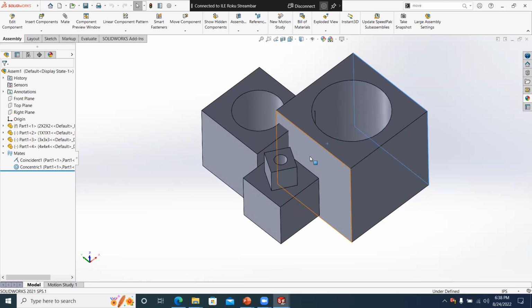Now they're separate, so you control the configurations within your part, and then the assembly is managing each of those parts on its configuration level. So if I brought in a pin to go inside of these boards, then I would have to also go in and say I need the 1/2-inch pin, I need the 1-inch pin, and manage those.